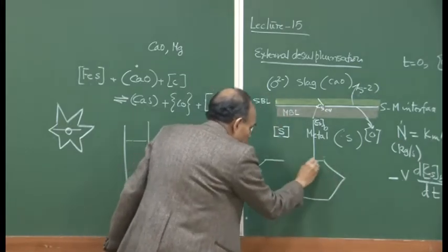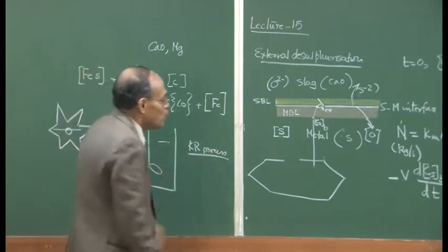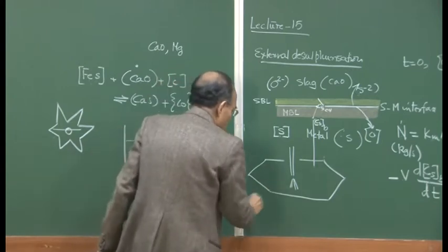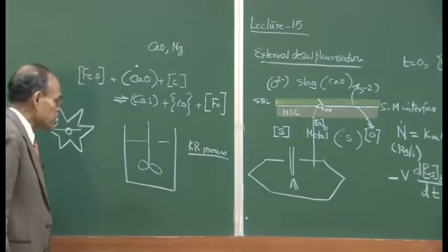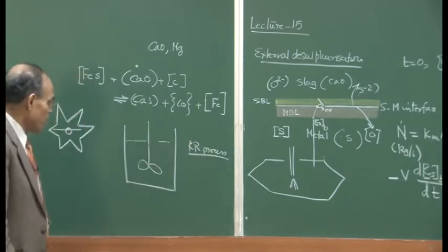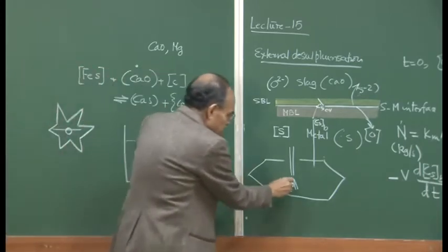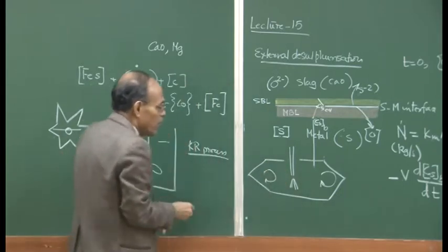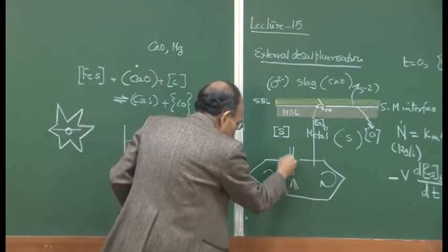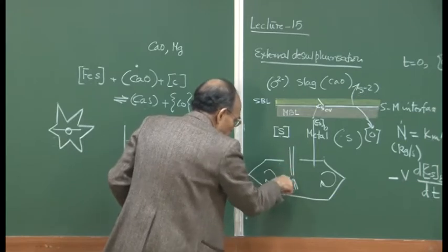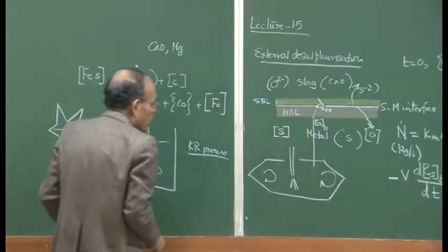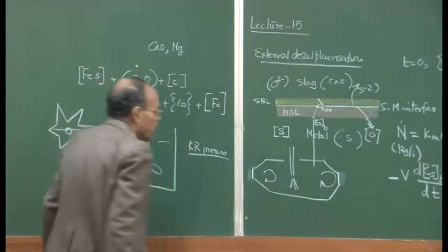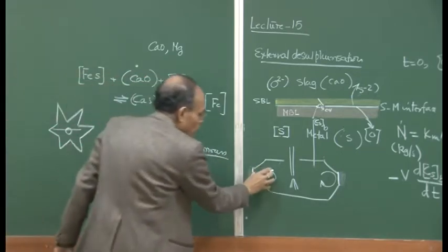Whether you do it in a ladle or in a torpedo, you will have to have stirring and injection of powder in both systems. They have their own inherent advantages. These are shallow vessels. One single stirring may not be quite effective to produce a good amount of stirring here. So, there is a region of intense stirring which is located close to the injection nozzle, while regions far away could be a little bit poorly stirred, not so well stirred.